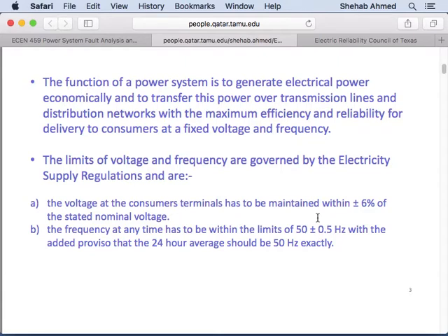That transformer was operating at what frequency? 10 kilohertz or 12 kilohertz. I don't remember what exact frequency was selected, but it was a very high frequency, right? And that transformer was pushing about half a kilowatt, so 500 watts maybe, through it, and it was this small. If I tell you to go buy me a 50 hertz 500 watt transformer, it will be this big. So the size of the transformer is inversely related to its frequency.